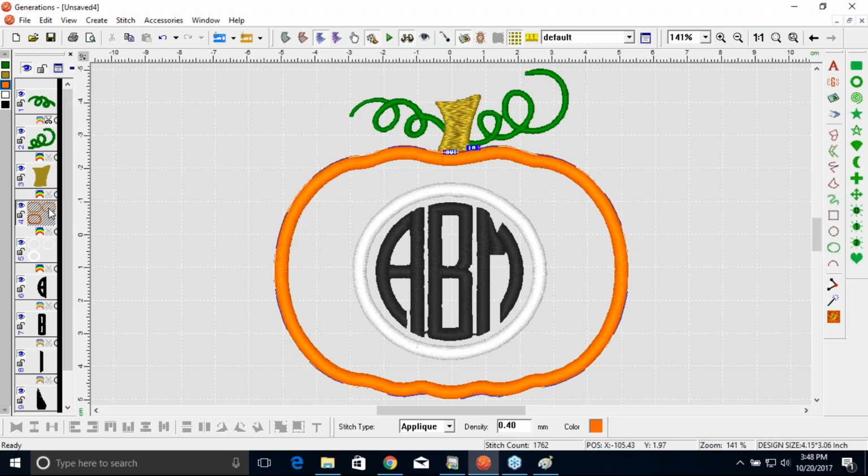So you're going to have the placement stitch. It's going to do a stitch exactly where that fabric needs to go. The machine will stop, you place the fabric down onto the material, and then it'll say to change your thread, but you really don't change your thread. Then go ahead and stitch again, and that's your tack down stitch. After that, the machine will stop and say, hey, change your thread. You're really not changing your thread, you're just going in there and cutting it. Then you'll hit start again, and it'll do the cover stitch.